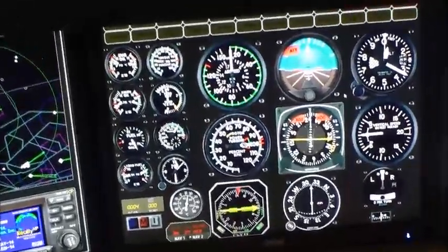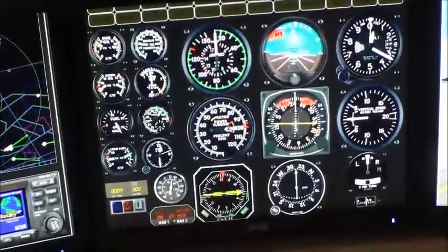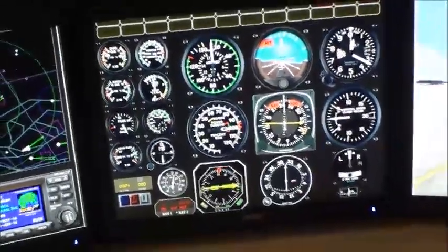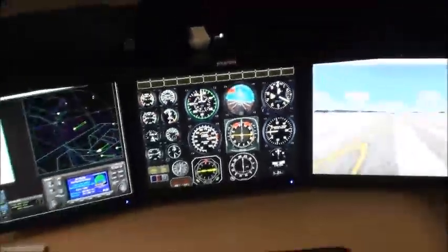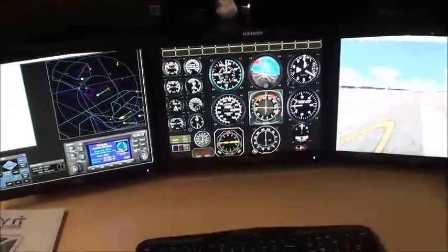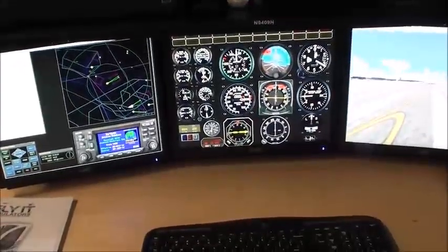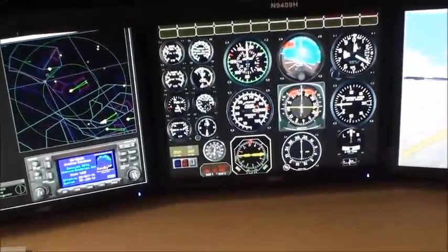So we have an attitude flag, so you have failed that gauge. Yes. As you can see, the gyro is spinning down, and it's falling like it would in the real aircraft, unless you get it completely seized. Some of the other failures you won't notice until we're actually flying, such as the pitot system would affect the airspeed. If we fail the altimeter, that needs to be demonstrated while we're flying. We'll go ahead and do that now.